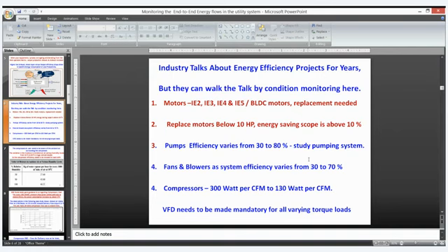And a VFD for a variable torque load, especially for blowers and fans and for some of the centrifugal compressors and pumps, is becoming mandatory. So instead of waiting for the OEM or the management to decide, you take the call and go for a VFD on the existing system, because this will optimize the torque and the speed of the given motor to give the equipment what it needs to optimize the production for the day, the week or the month. This is more important. It is very user friendly, and each and every industry has gone for the VFD, especially on variable torque loads.